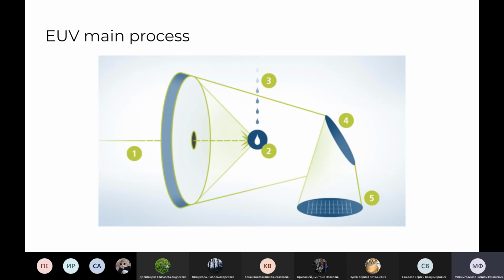In the installation for the production of processors by EUV lithography, which we will talk about separately, a special carbon dioxide laser with a power of 30 kilowatts is installed, which shoots two pulses at a frequency of 50 kilohertz. The laser hits thin drops. The first shot flattens the drop and turns it into a pancake, which becomes an easy target for the second volley, which sets it on fire, and it happens 50,000 times a second. And the resulting plasma emits light in the extreme UV spectrum.